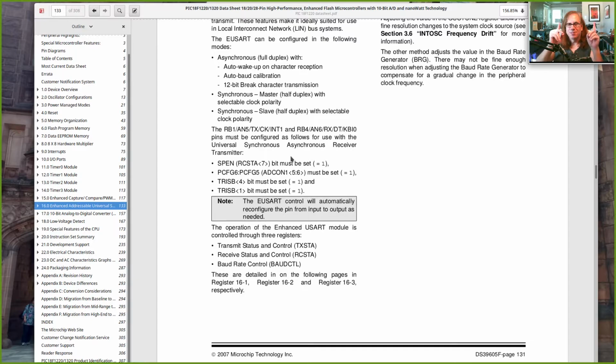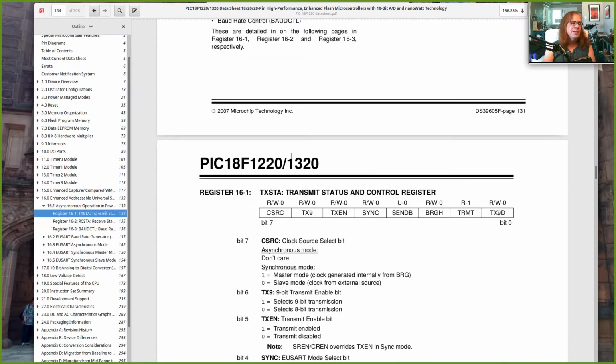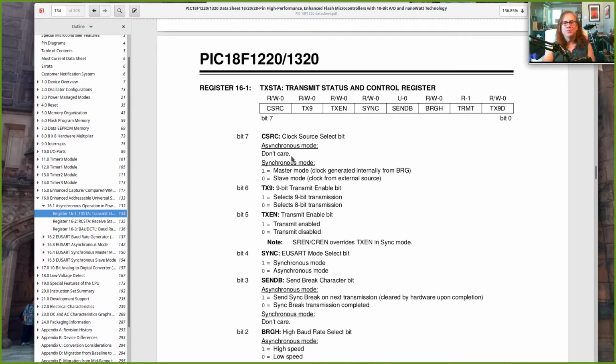Because, a nanosecond per foot. So if you had a 12-foot USB cable, the time delay was great enough that you would get clock skew that would corrupt your signal. But I think the clock is understood in that, but I could be wrong. And it depends which USB. By the time you get to USB-C, it's all sort of extreme.